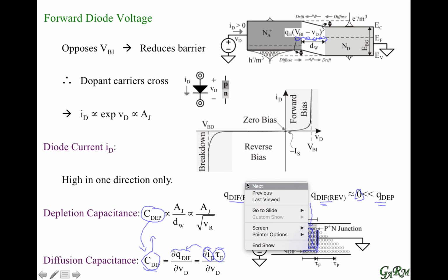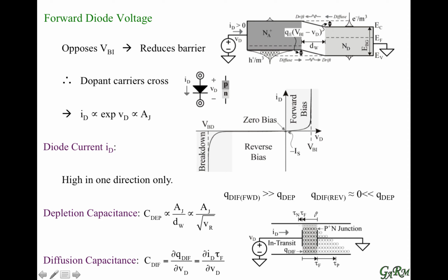Something very interesting, and we're going to remove markers here, is when we're in a forward bias condition and we want to go into reverse bias, well, these charges that were in transit are going to stop moving, but in fact we're going to have to pull them back. So there's going to be a momentary reverse current to basically drain this depletion region of diffusion capacitance.